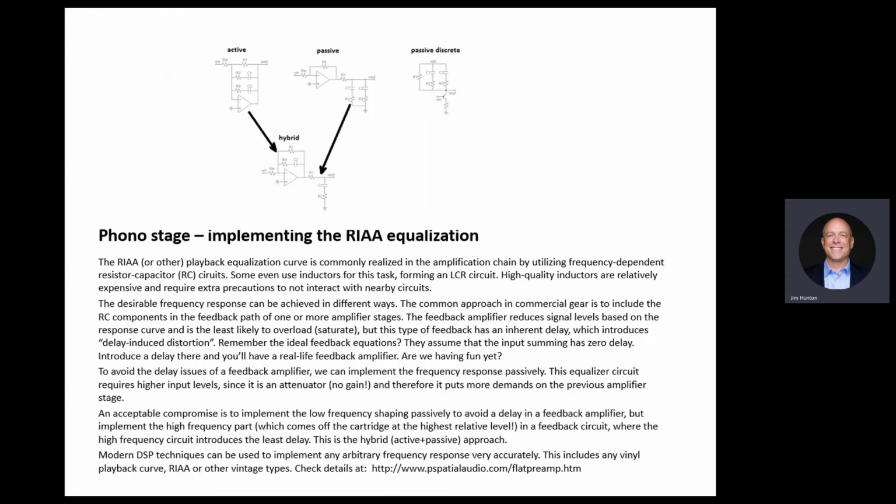Usually I don't use op amps, so I just took some circuits. But you're right, you can make that the positive input, non-inverting. Usually in the input stage at least, you'll use something like a JFET, which is essentially high impedance, so you don't have that problem. Maybe I'll change that. But it's an easier example. I don't want to put transistors with the whole circuit in there, so an op amp is easy.